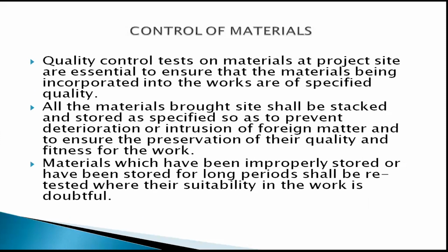Control of materials. Quality control tests on materials at project sites are essential to ensure that the materials being incorporated into the works are of specified quality. All the materials brought to site shall be stacked and stored as specified so as to prevent deterioration or intrusion of foreign matter and to ensure the preservation of their quality and fitness for the work. Materials which have been improperly stored or have been stored for long periods shall be retested where their suitability in the work is doubtful.